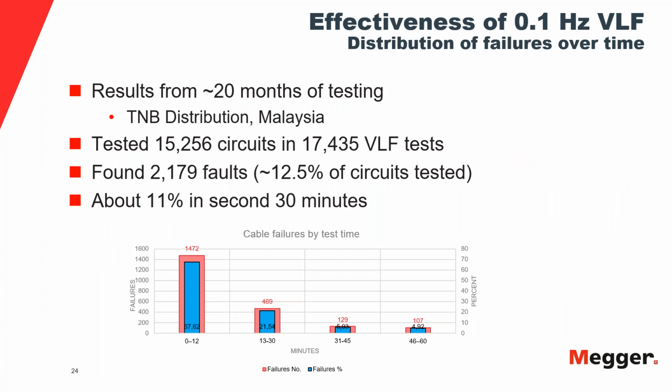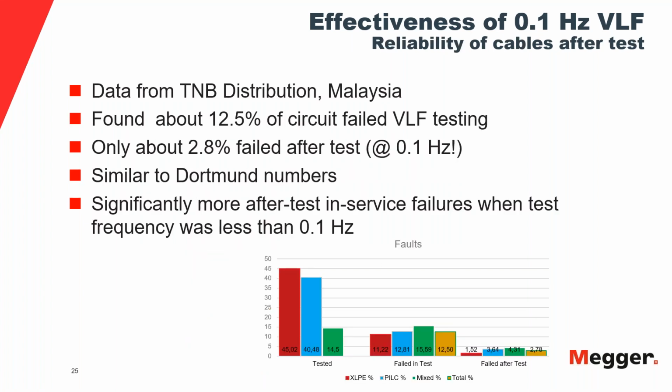And now I told you about the study. There was the study in Dortmund where they tested quite a bit of the network and validated this 97%. And there was another big international study at TNB distribution in Malaysia, and they tested like crazy. They did more than 17,000 VLF tests. And funny enough, very different country, very different network, very different underground infrastructure, same numbers as in Dortmund, or let's say very similar numbers.